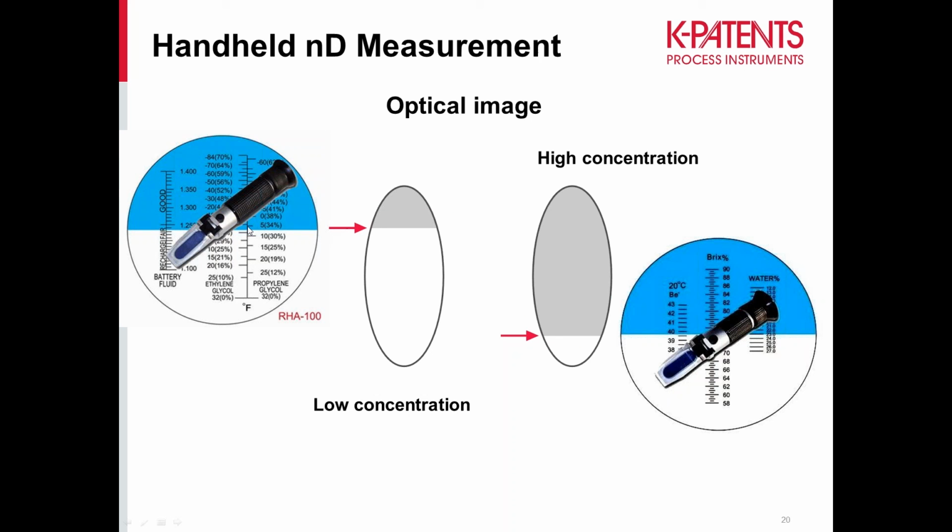but that calibration scale can also be other things such as Brix, which is very common when you're buying them from any kind of catalog house. Online refractometers: well, that principle is the same thing in online process refractometers. That optical image is created by the phenomenon of refractive index and projected onto a CCD camera. That's a digital camera. The digital image is shown on the refractometer.